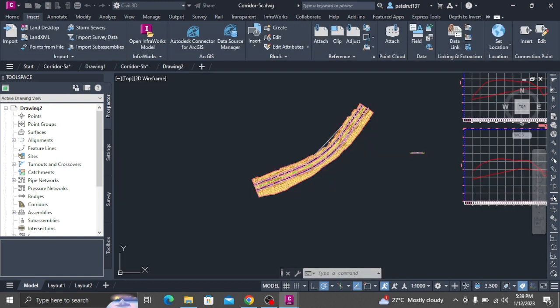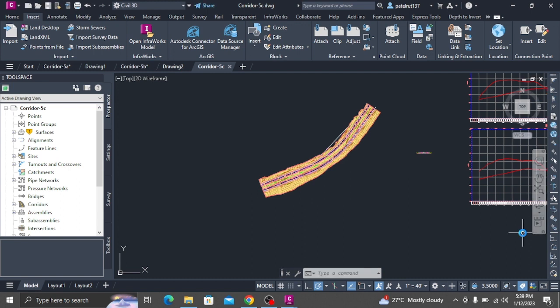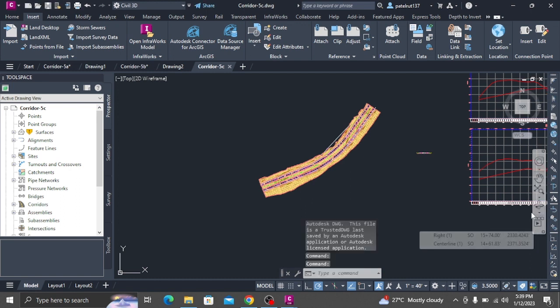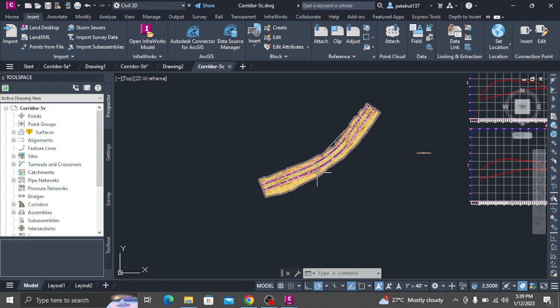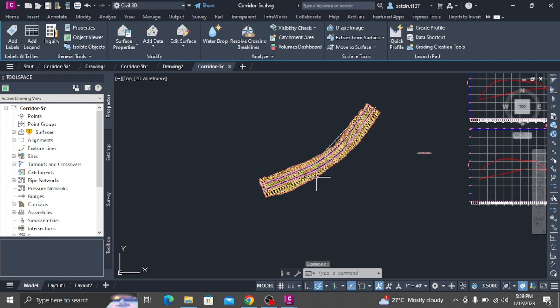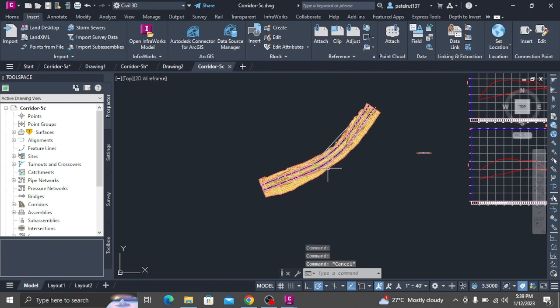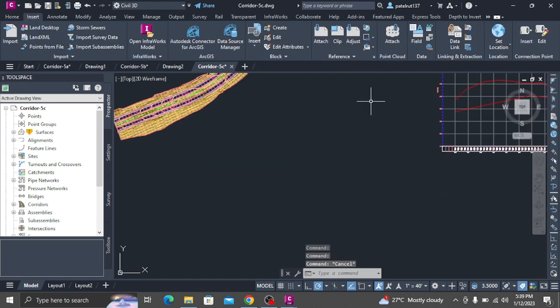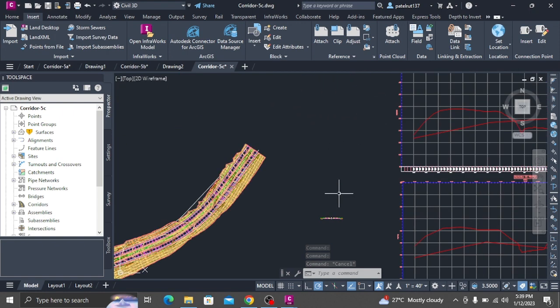Open Corridor 5c.dwg, which is available in the Tutorials Drawings folder. In the drawing, select the corridor. Click Corridor tab, Modify Corridor panel drop-down, Edit Code Set Styles. On the Edit Code Sets dialog box, under Code Set Style, make sure that All Codes is selected. Daylight_cut, Site Work, Planting, Grass, Short.